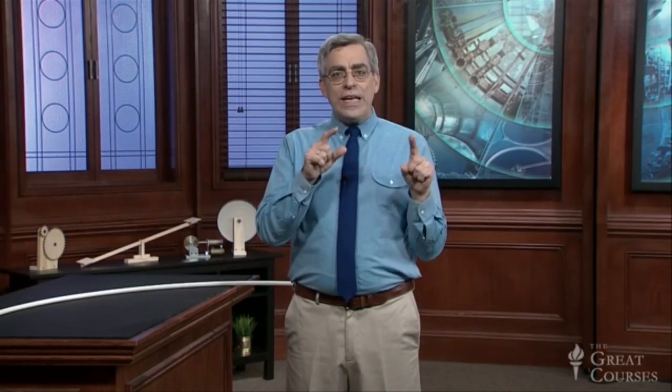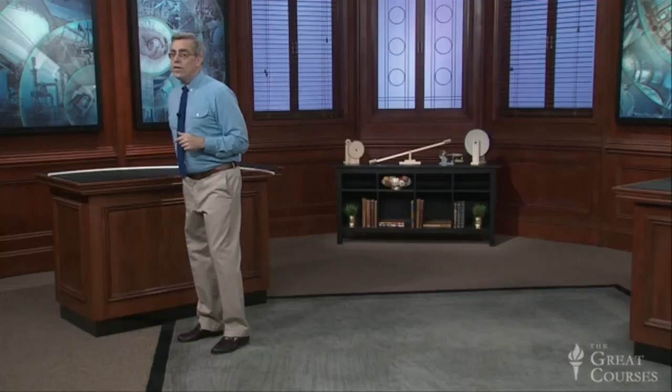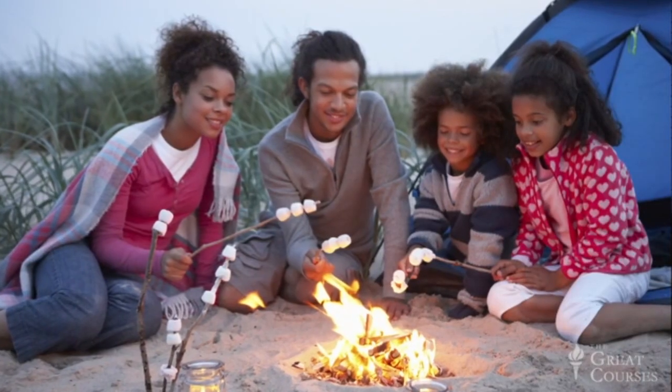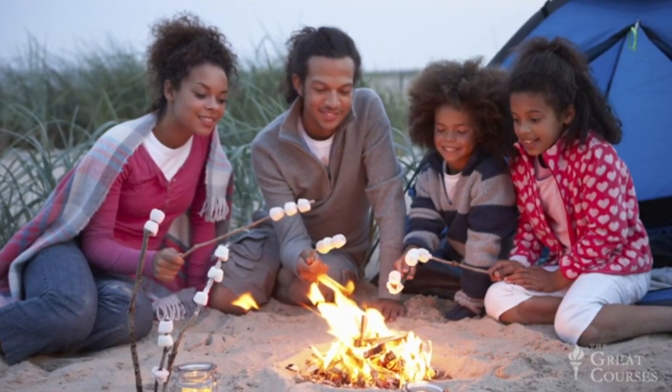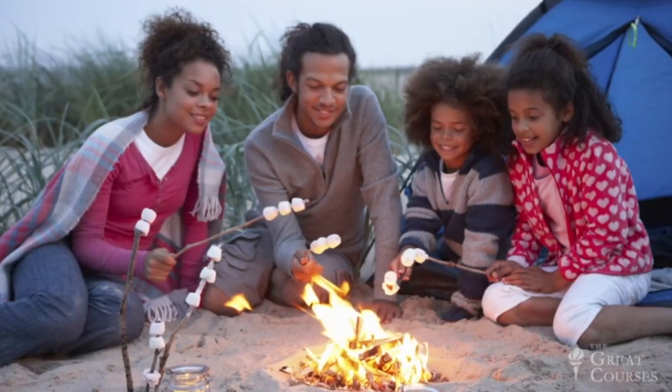The slab in turn heats the room by a combination of radiation, conduction, and convection, with more heat transfer by radiation than any other form of heating, except perhaps the fireplace. And herein lies the source of the energy efficiency that's prompting so much enthusiasm for radiant flooring. It turns out that heat transfer by radiation makes us feel warmer than heat transfer by convection. You actually experience this every time you sit by a campfire. Did you ever wonder why, as you look at the fire, your face feels warmer than your back, even though the air temperature in both places is the same?